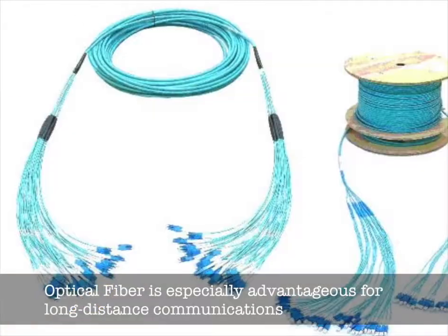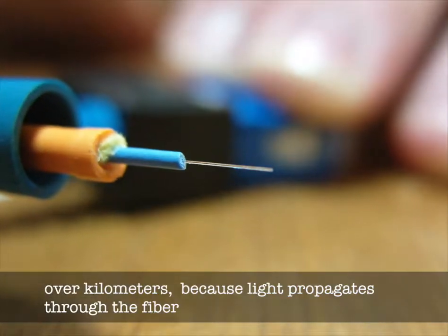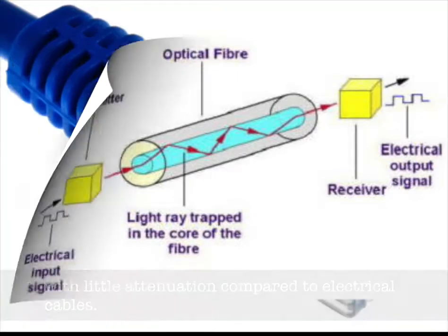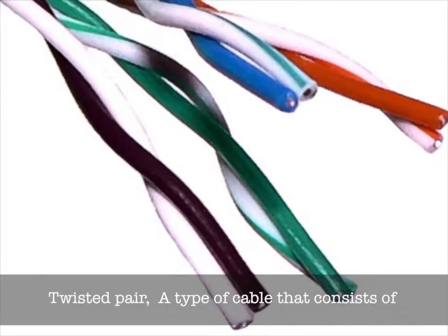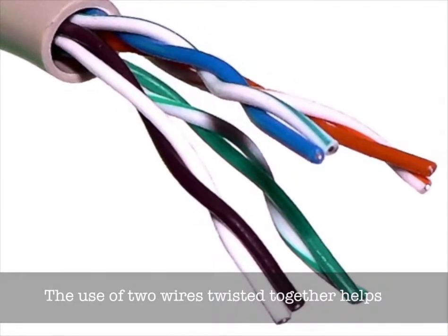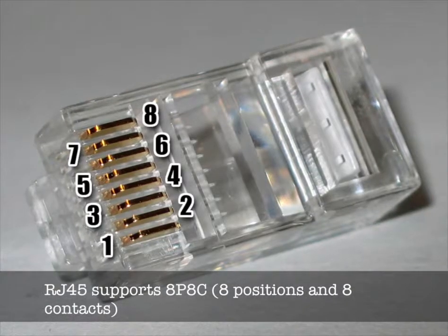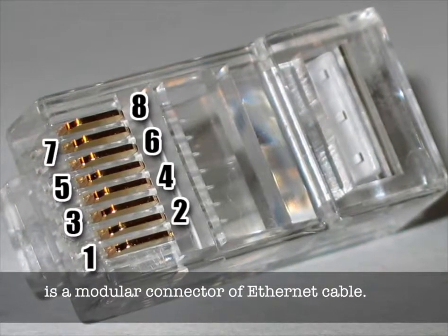Optical fiber is especially advantageous for long-distance communications, over kilometers, because light propagates through the fiber with little attenuation compared to electrical cables. Go back to Ethernet cable. It includes twisted pair and a connector. Twisted pair, a type of cable that consists of two independently insulated wires twisted around one another. The use of two wires twisted together helps to reduce crosstalk and electromagnetic induction. RJ45 supports 8P8C, 8 positions and 8 contacts, is a modular connector of Ethernet cable.